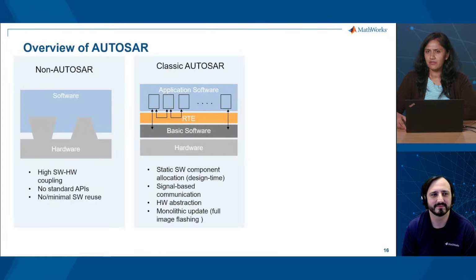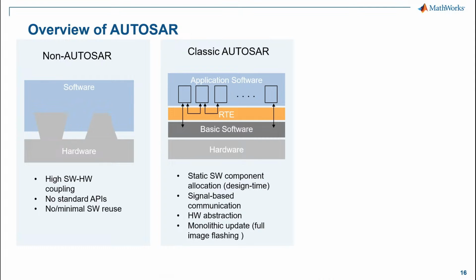All right. I thought of introducing you to AUTOSAR by identifying the difference between AUTOSAR and non-AUTOSAR architecture. As you see here, in the non-AUTOSAR architecture, the application software and the hardware pieces are tightly integrated. And the layout looks really rigid, and the application software is dependent on the hardware. Whereas in the AUTOSAR Classic layer, all the layers have been modularized, and the application software is abstracted from the below-level software like basic software services, and also independent of hardware.